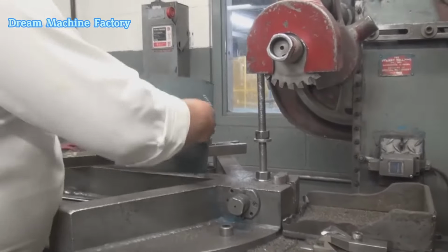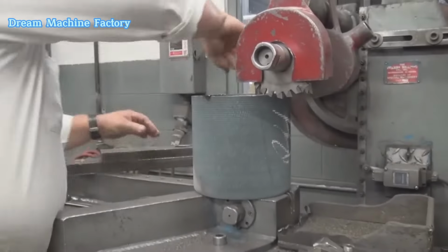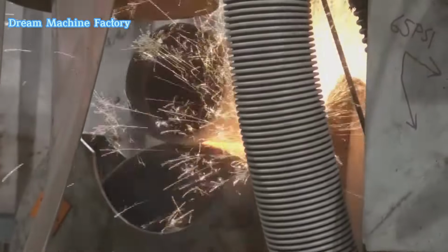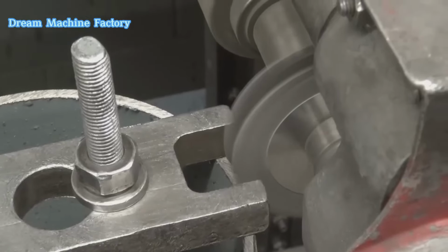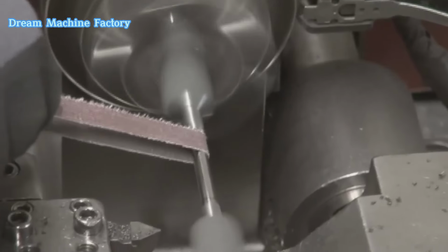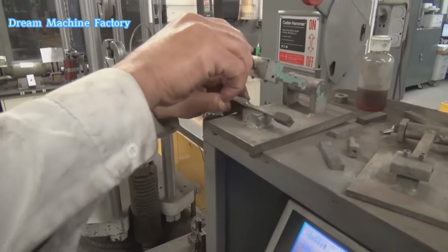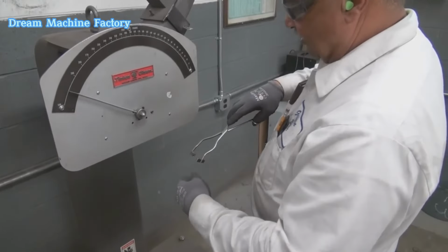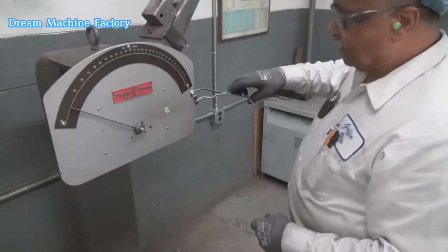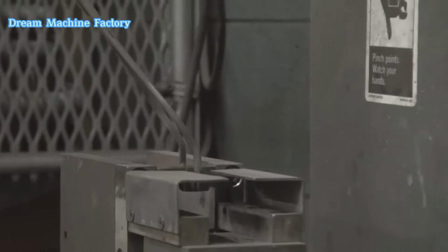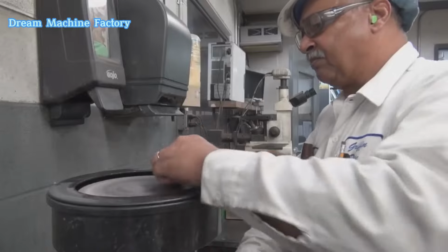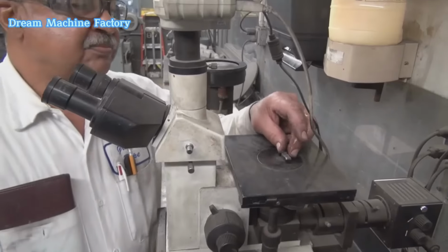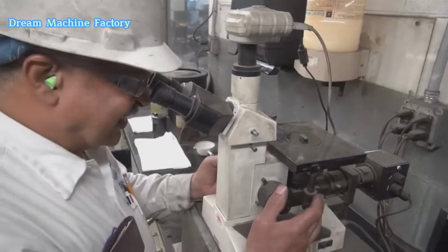A hydrostatic pressure test is performed on every pipe, where water is pressurized to 500 psi for 5 seconds to confirm structural integrity. Additionally, mechanical tests are conducted, including tensile strength, yield strength, elongation, and impact tests. The Charpy impact test checks toughness at both room temperature and -40 degrees Fahrenheit to ensure the pipe resists brittle fractures in extreme conditions. Microstructure and ultrasonic velocity testing further verify the pipe's internal consistency.